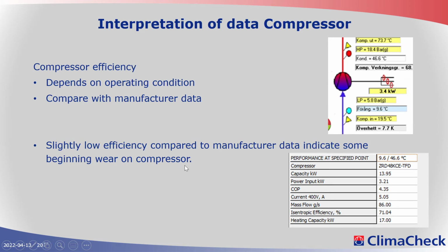So this compressor is just slightly below the new compressor, but absolutely not seriously. So it's very easy to check that your compressor performance matches design for all those compressors that are available as service compressors. I mean, Copeland, Danfoss, Bitzer, Frascold, and many others have software available on the internet.